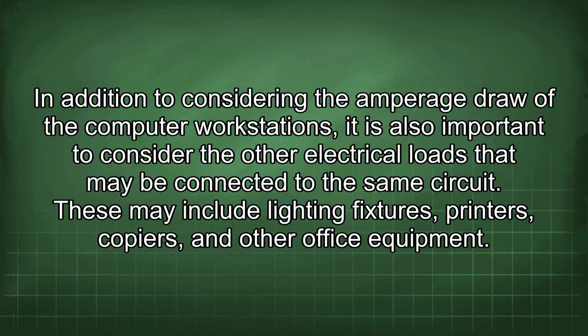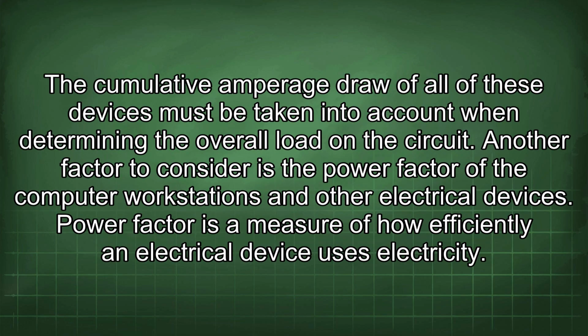These may include lighting fixtures, printers, copiers, and other office equipment. The cumulative amperage draw of all of these devices must be taken into account when determining the overall load on the circuit. Another factor to consider is the power factor of the computer workstations and other electrical devices.